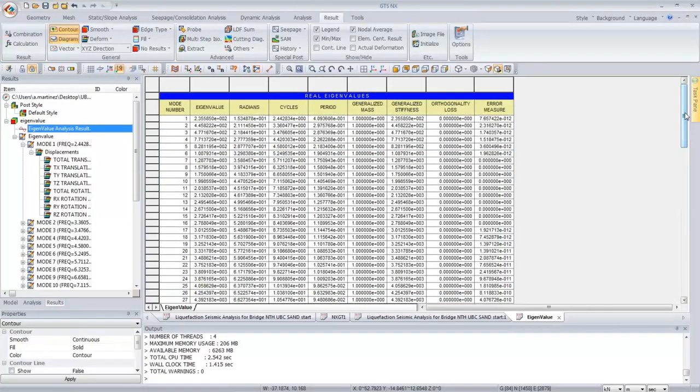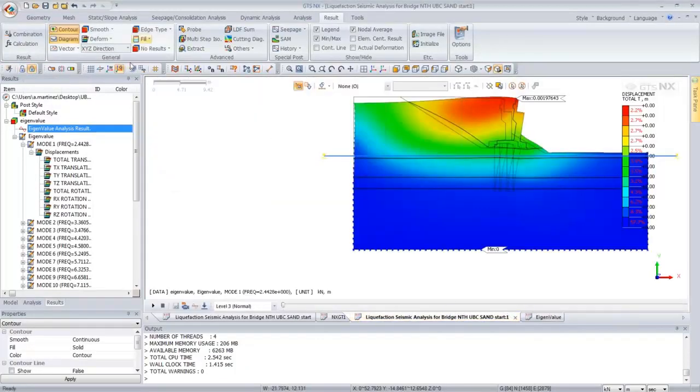So we go back to the top of the box, and we would write down these periods or frequencies. In this case, I'll just do periods. So I'll write down that 0.409 and 0.190, or in those ranges. I would write it down in a box or somewhere. And those are the values that I'm going to be inputting later for my Rayleigh damping in the nonlinear history analysis. So you can take a screenshot, write it down, or whichever it is you need to do. But we would go back to the pre-processor mode in the model, which is here.